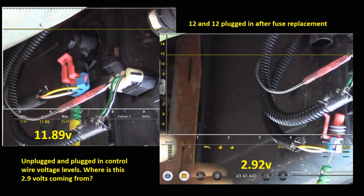This is after replacing the fuse. I'm doing the same measurements with it plugged in with a good fuse. I should have shown both, two pictures. I'm reading 12 volts here, and I'm reading 12 volts here. I know it says 11.89, key's been on for a while, battery voltage is low. I see 12 and 12. Isn't that what we want to see on a ground side switch circuit? And so then I say to myself, well, okay, where was that voltage coming from? And I said to Caleb in the video, oh, that's a bias voltage. And I proved it in this capture.